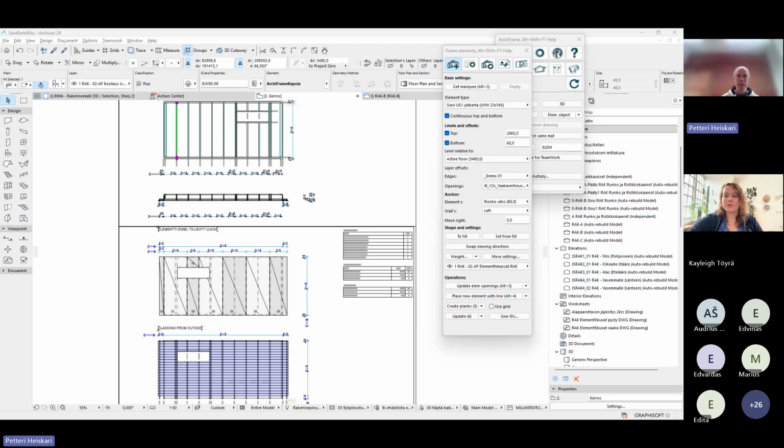So you can have it, or you can have any kind of reference as read only. For ArchiFrame, if it's editable, the source wall where you add, for example, where I added this one, then ArchiFrame is able to add more information that enables copy paste between Archicad.